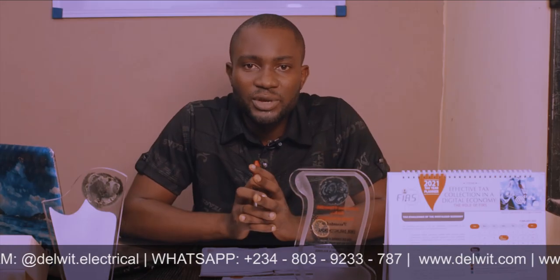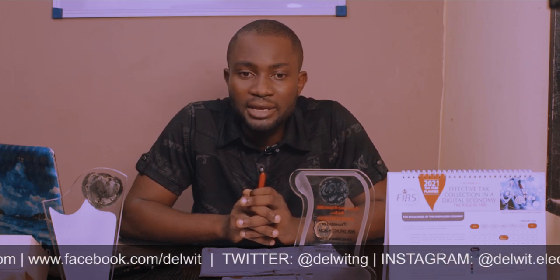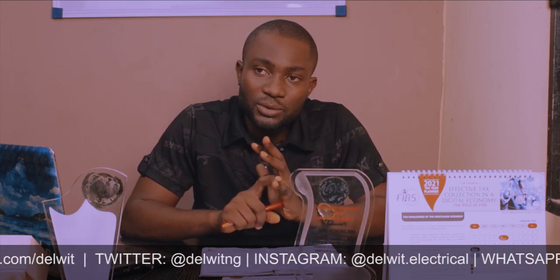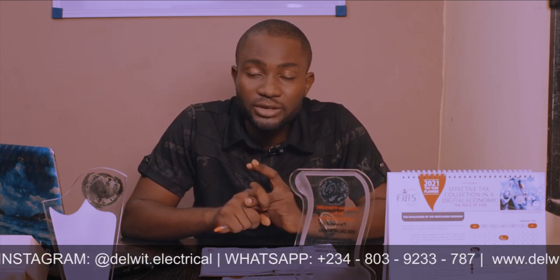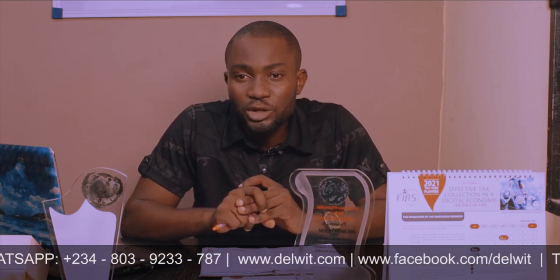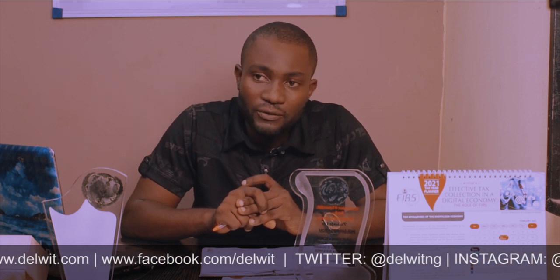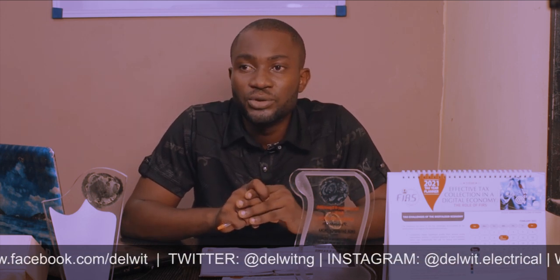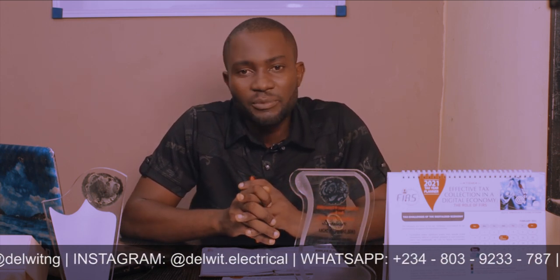So I believe I've been able to educate you on how to choose the right inverter for your buildings. We've talked about 4 major points which I advise that you take into consideration before buying your inverter system. You have to consider the power requirement of your building. You have to consider the VA rating of the inverter you want to buy. You also have to consider the output waveform that is required: a square wave, a modified sine wave, or a pure sine wave. And you also have to consider the phase: single phase or three phase.